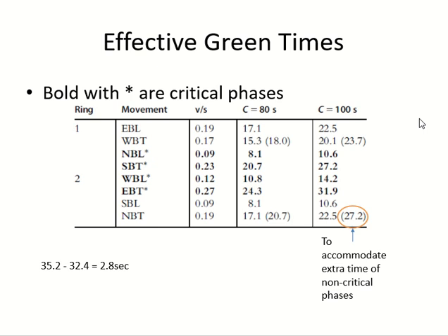Let me add all 3 seconds here. Or add all 3 seconds here because this is already lower, and so on. Or add equally, 1.5 there, 1.5 there. No problem with that, because I am just trying to adjust the timing for practical reasons. Traffic is already satisfied. But they are saying the common practice is we add it in the through movement only.